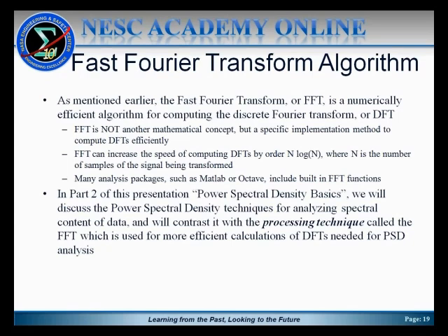In part 2 of this presentation, Power Spectral Density Basics, we'll discuss power spectral density techniques for analyzing the spectral content of the data, and we'll contrast it with the processing technique, if you want to call it, of an FFT. As I said before, the FFT is really not distinct from a PSD. You can say, well, can I get the same information that I would get from a PSD with an FFT?